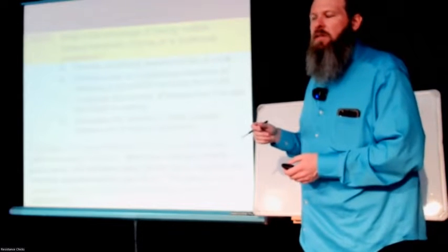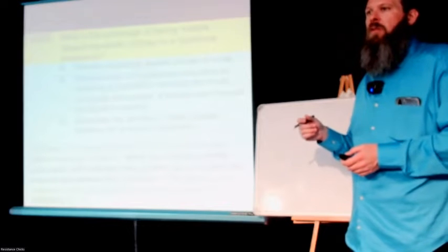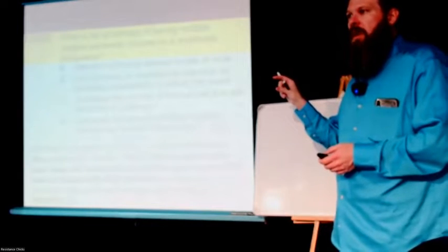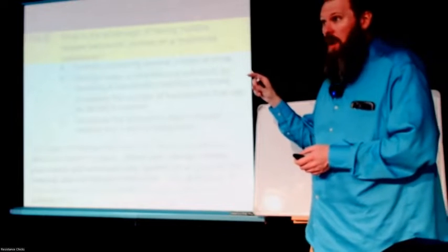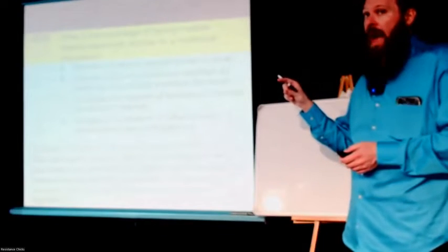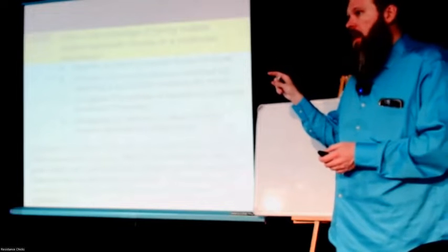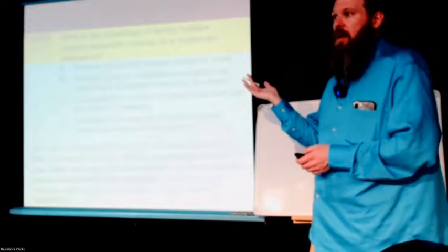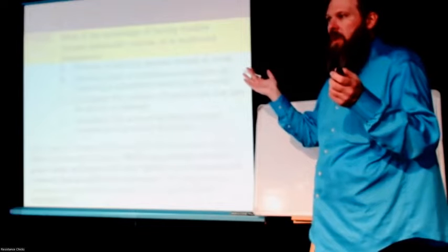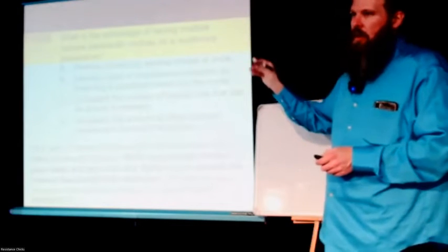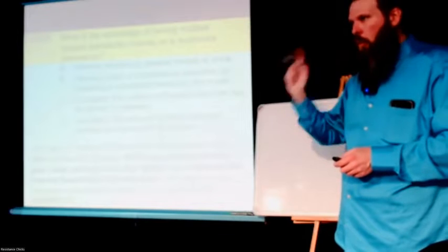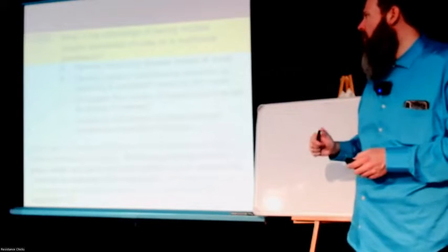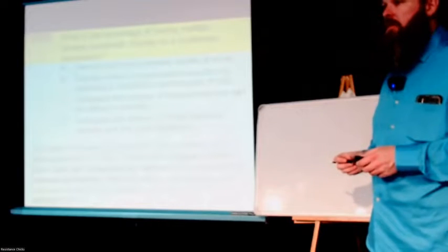You probably don't want to listen to a Morse code transmission with the 3 kilohertz bandwidth because, as we talked about, you could fit 20 Morse code conversations in there. And if you have a 3 kilohertz bandwidth on your radio and you're listening to that Morse code conversation, you could potentially hear 20 conversations simultaneously. It would sound like a bunch of noise. You'd want to select a very narrow bandwidth to be able to hear the one conversation that you're trying to listen to. And so that's what they're talking about. That's what the advantage is so that you could reduce noise and interference.